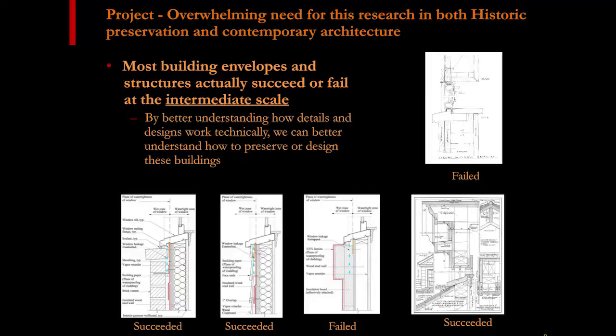And in my experience and all the forensic work I've done at SGH looking at building failures and building problems, it's that intermediate scale that's really critical to durability. That's where buildings live or die. So, here are 5 window sections. That's the intermediate scale. So the nitty-gritty of how a window sill is married to cladding, how a flashing is married to backup waterproofing, building paper, that type of thing is really critical to design.